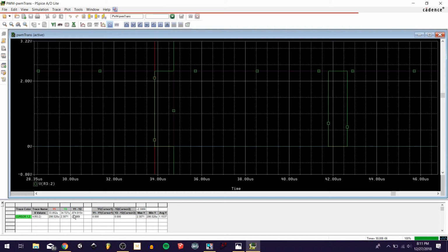So that's about 874 nanoseconds, which is 0.874 microseconds, if you remember. So my low time is about 0.874 microseconds. And the high time, I've got the green cursor on the beginning of the high, so I'm going to take the left cursor, the red one, with a left click and bring it to the other side. And that guy's about 7.007 microseconds. So the high time 7.07 microseconds, and the low time was 0.86, I think, microseconds, something like that.